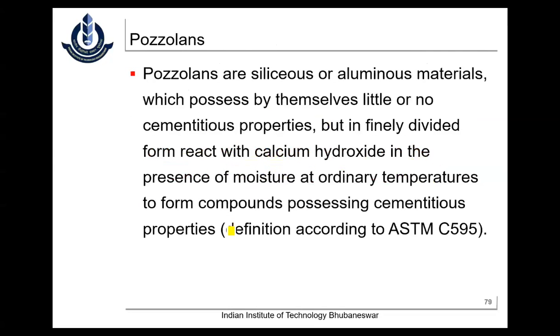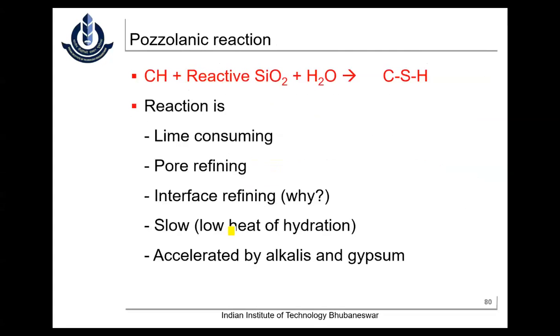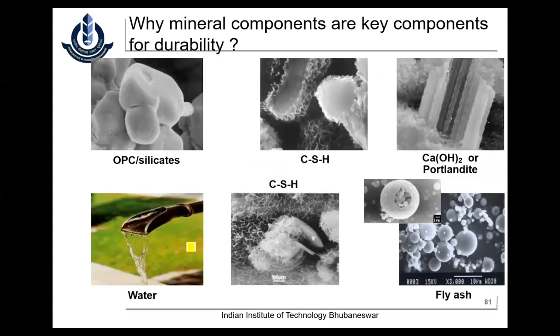So we all know about pozzolans and the pozzolanic reaction. I got this from one of my earlier companies. When OPC cement reacts with water, you get a hydration product called CSH gel, and you get a weak compound called Portlandite, or calcium hydroxide.